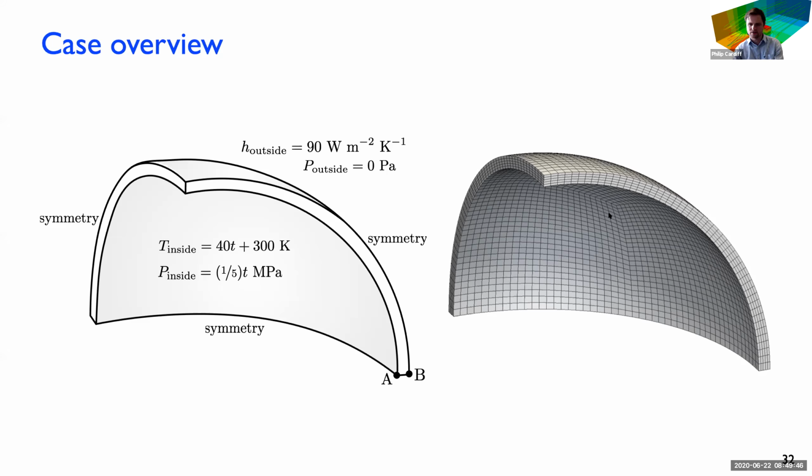This is the mesh I created. There's no blockMesh in this. I'm actually using a mesh that I've temporarily stored in the Fluent mesh format. Strangely, when I went to make a mesh of a sphere, most versions of OpenFOAM, the way they apply curves, cannot do spheres exactly. One version of OpenFOAM, I think the Foundation version, has a blockMesh that can exactly reproduce spheres, but the other ones can't.